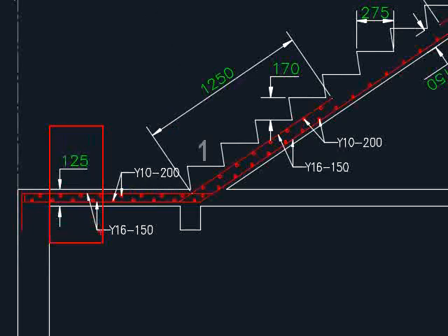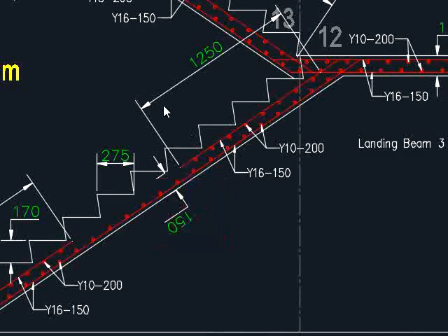Clearly indicate the thickness of the slabs of the ground floor, the riser, the steps, the thickness, the anchorage length, and how the reinforcement bar should be laid. Remember that the reinforcement bar can only go in the straight directions for the maximum performance instead of being bent here and there. As for the arrangement of the reinforcement bar, it should be something like this. You have a straight bar being bent in these directions. You also have a straight bar here being bent in these directions.